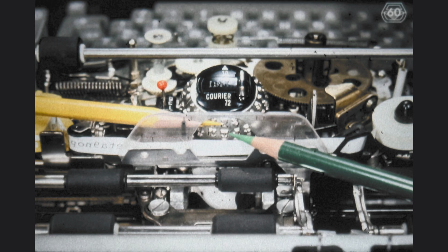We studied earlier that all motions of any parts caused directly by the action of the motor are called positive motions or positive actions, and that all motions caused by the action of springs are called negative actions. It is very important that during the upcoming discussions we keep these facts in mind. Even to a relatively unskilled observer, it is quite apparent that we must be able to tilt and rotate the type element in precise increments of rotation.